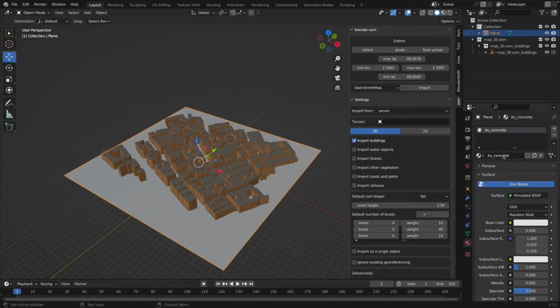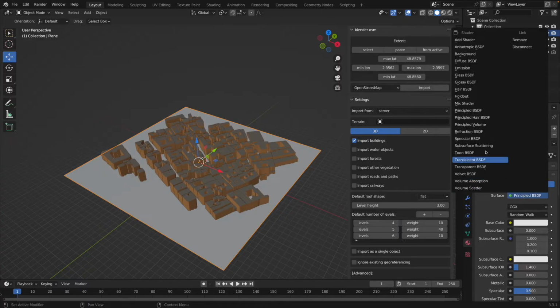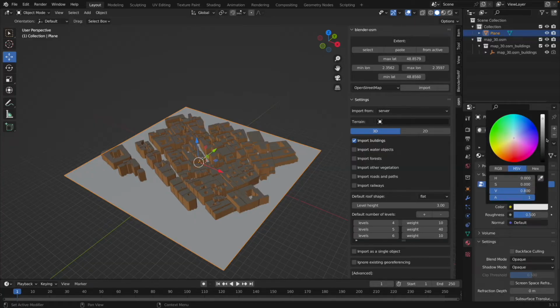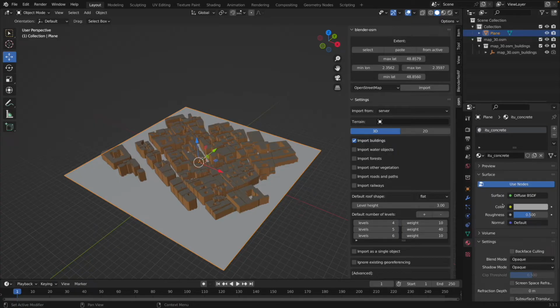Once we have set the name of the material, we can also define properties for its rendering, that is visualization. For example, let's use a simple diffuse BSDF, and then let's set the color to a different value. Notice that these properties will also be used by Sionna for rendering, that is for visualization. Once we have set the radio material for the ground plane, let's do the same for the other elements of the scene, that is the buildings that were imported from OpenStreetMap.